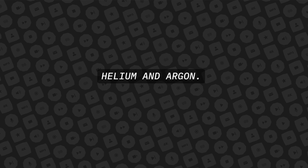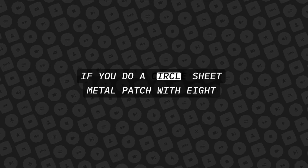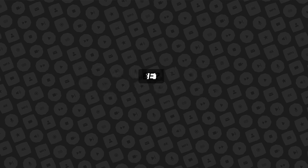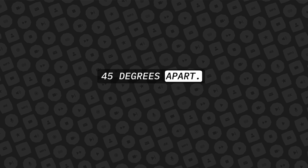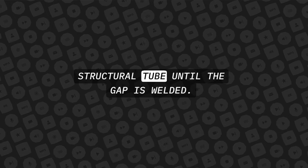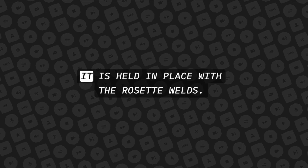What type of shielding gases are used for gas tungsten arc welding? Helium and argon. If you do a circle sheet metal patch with 8 rivets, how many degrees apart should the rivets be? 45 degrees apart. How is the inner sleeve tube held in the structural tube until the gap is welded? It is held in place with the rosette welds.